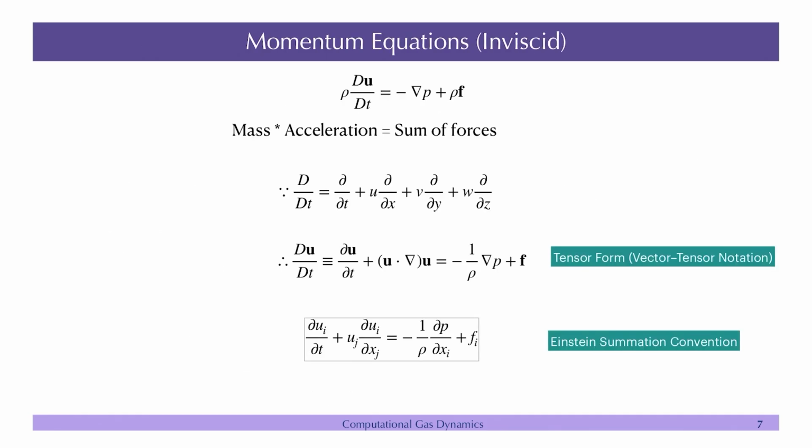Now, let us go to the momentum conservation, okay, and we will first discuss the inviscid relation, and then we will go to the viscous one, because they are slightly more complicated, right. As I was telling, momentum equations are nothing but the application of Newton's second law, which is mass into acceleration equal to summation of forces, and this is what you see here. Because we are talking about fluid, everything is per unit volume, so that is represented by density here, and the acceleration is basically the total acceleration du by dt.